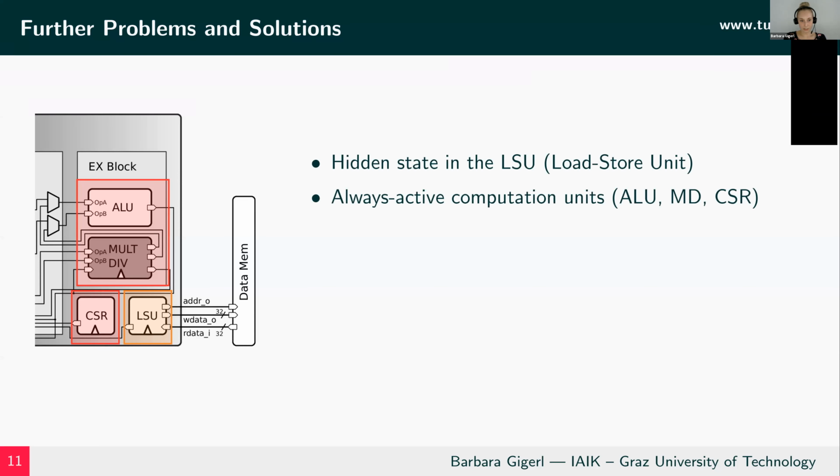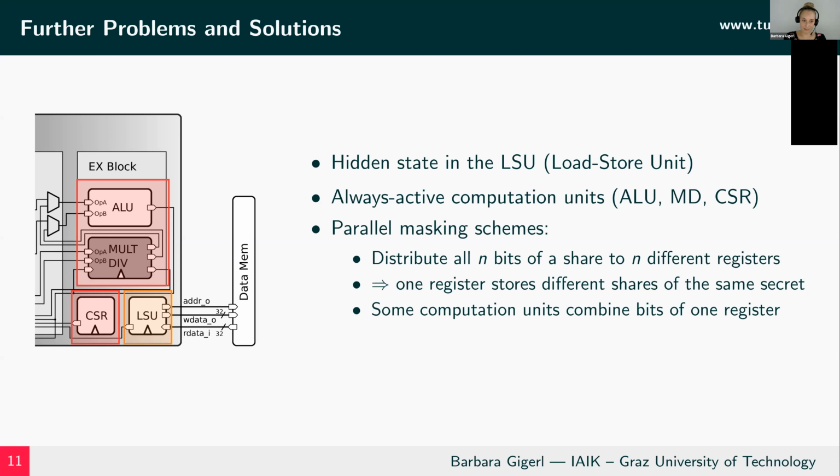Another thing were the computation units, so the ALU, the multiplier, and the CSR unit, because they were always computing. So if we, for example, execute a load instruction, the ALU would still compute the XOR without it being needed. And this specifically creates leaks when you want to use parallel masking schemes.